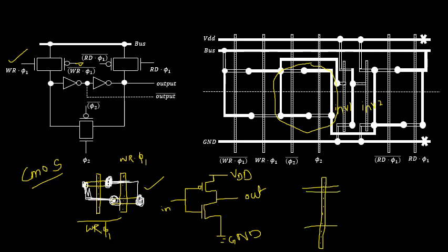This is N type of diffusion layer, and the P type of diffusion will be connected to the VDD, that is nothing but a metal layer. So obviously here I am supposed to make use of a contact cut. Then I am having a metal layer used for the ground terminal. So just for the clarity, I will erase it.